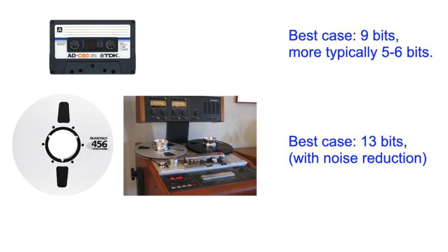Tempo resolution doesn't matter so much here because it's analog. So the analog recording is continuous. And so we have very, very high sampling frequencies, or the equivalent of high sampling frequencies, because it is analog. But the functional depth of the recording, the resolution of the amplitude, is actually very modest. It was not spectacular. Now, I used to work in studios years ago, and there we had very high quality tapes, much more expensive, big wide tapes, and there the best case we ever got was 13 bits, which you'll remember is still nothing close to what we have in everyday devices around us. You have devices in your possession that have higher resolution than that. And again, these are still analog recordings.